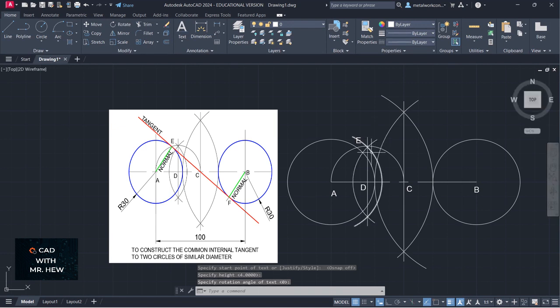All right, now remember I told you I'm going to break this line. The arc is running through the E, and it's just for neatness why I'm going to break it. So we're going to break, select the arc, enter. When I click right here, enter. I'm going to do the same thing here, just for balance, enter. So when I click here, I press delete, and now the arc is removed, right?